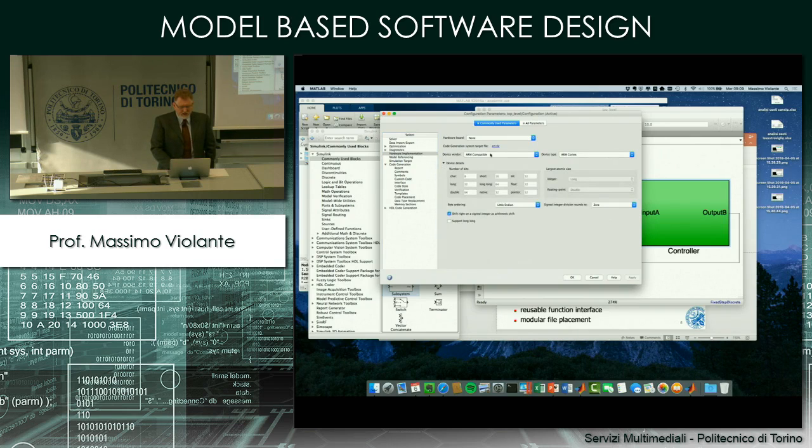In particular, you can select the board you want to use, and here you have a list of options depending on which packages you have installed in your Simulink, in your MATLAB system. For the moment, I think you haven't installed any platform support package, so it is very likely that you have here either none or Get a hardware support package. You shall not have Cortex M3 QEMU or Freescale Freedom K64F. Not yet. When you install the platform support package, you will have that.